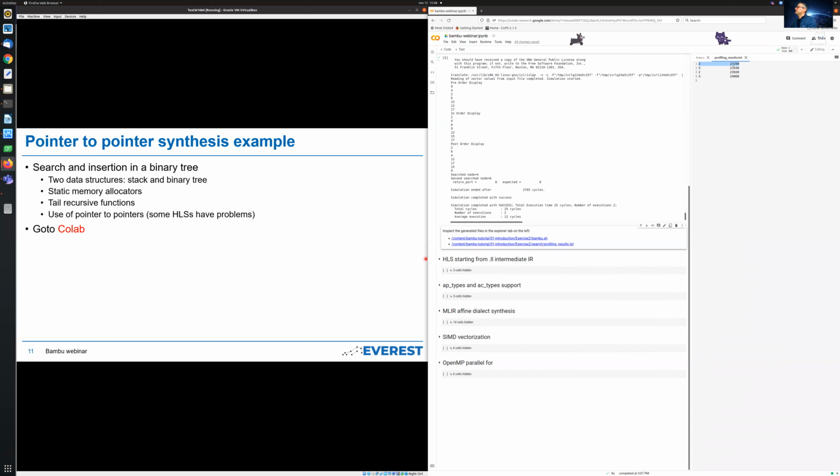If you do the difference between these two numbers, you are going to have the exact number of cycles for the first search. The same way, the total number of cycles for the second search. So you may have very fine-grained profiling of the function by performing the simulation of the Verilog with the instrumented code.